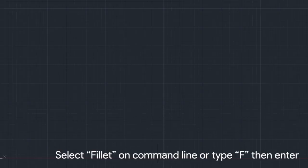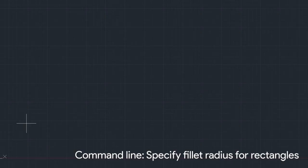Okay? So that is our chamfer. Our fillet, press F. It is similar to the chamfer, but instead of slicing, the fillet smooths, it rounds. What the fillet asks for is the radius. The chamfer asks for the first distance and second distance. The fillet asks for the radius. So let's just say the radius is 2. And first corner and second corner.